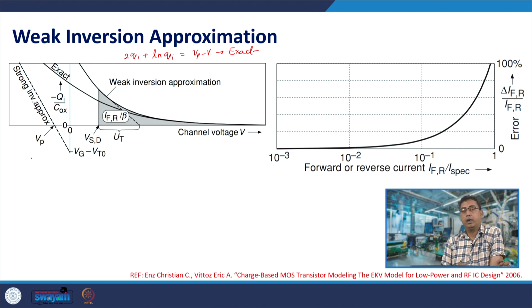So, when the gate voltage is larger than Vto and Vs is say 0, in that case near the source, the channel is inverted, but since you have a VDS which is positive, as you go towards the drain, you keep on reducing the inversion charge, and for Vd greater than Vp, you would find that the channel pinches off for local channel potential equal to Vp.